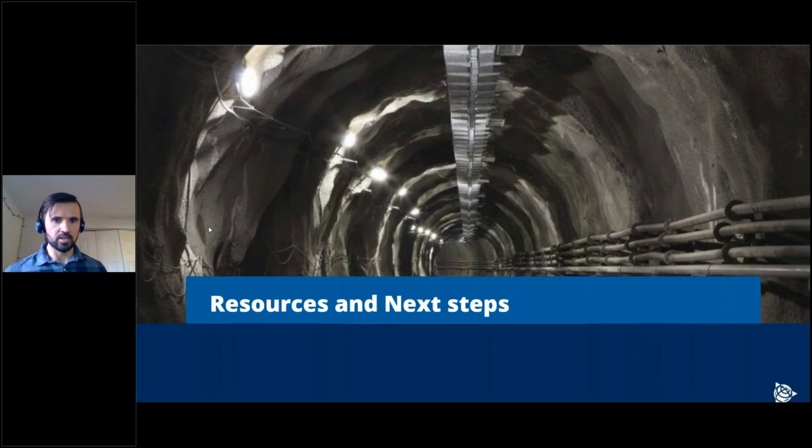So if I set up my instrument and I did a resection to my tunnel control points, that scan is referenced to that control. And so if I do that again, so they spray the shotcrete and I scan again, I do the same thing. I set up to the control and I scan. And so those two scans are in the same coordinate frame. They're referenced essentially to each other. So you don't have to worry about that.